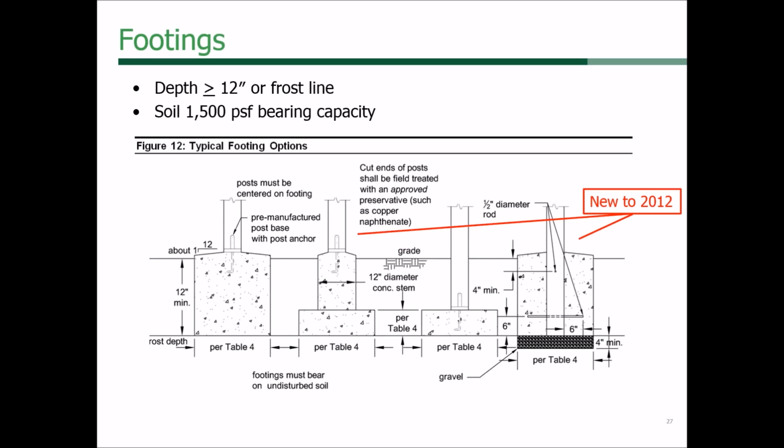Okay, so here's the footings. Again, we added 2 footings. One's kind of like a sonotube type situation, and the other one is this embedded post, which is the far right, that's actually from the post frame industry. It's an adaptation from that, so that you end up with a bit of moment capacity. The post can actually resist some bending.